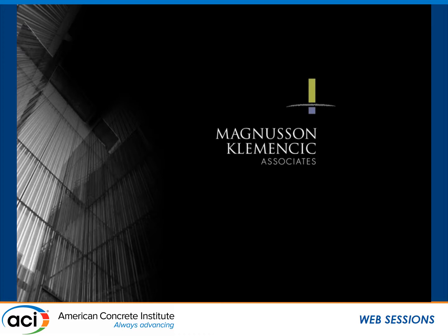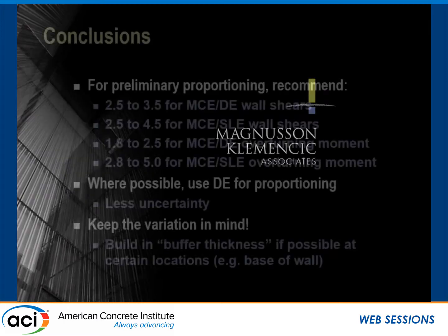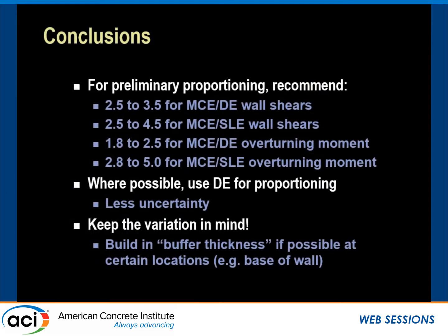Okay. What damping do you use in your study? Typically, it's 2.5% modal damping. Okay. I have a question regarding the ratio between the base moment you have for MCE and DE. I think the average was close to 2. What do you think is the reason why you have such a relatively large number?